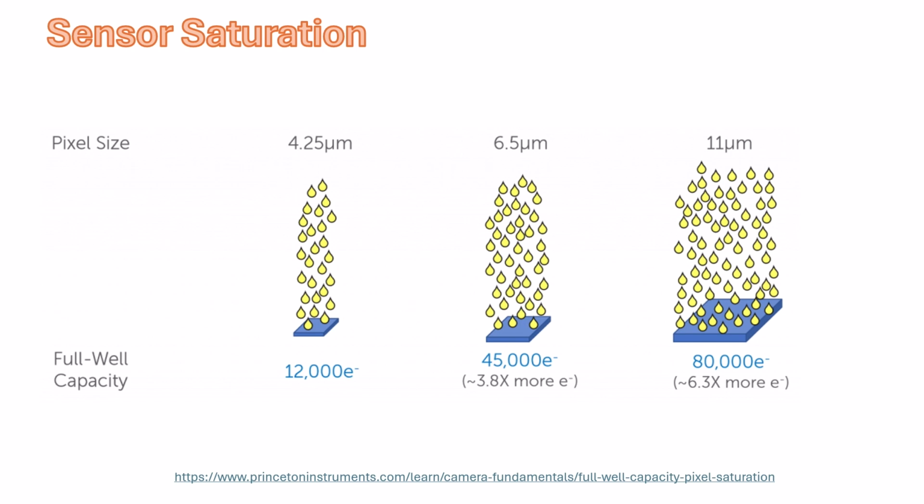When you digitize, you're going to read out this charge off of the detector and digitize it. When you digitize it, of course, you'd like to accurately reflect the signal. But if you digitize with too many bits, then you're just digitizing noise. So with 10,000 photons, the noise level would typically be around 100 photons. If you think about having the least significant bit representing some fraction of 100 photons, 8 bits is plenty of dynamic range to cover 10,000 photons. If we go up to a million photons, we might want up to 10 or 12 bits, but that's where typical focal planes are going to be, something that digitizes the signal with between 8 and 12 bits.